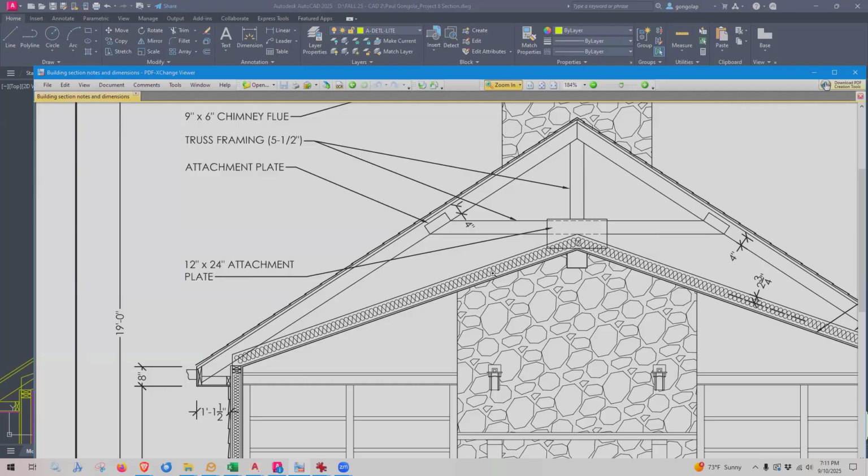You know what? I misspoke. This also is part of the truss too. So all of this framing gets put together in the factory, gets shipped out, and then with a crane they lift it up, and some guys are up on ladders over here. They lower one truss down, they attach it here, and then they put the next one in 16 inches, and then 16 inches further and further until they're all up. And then they'll often have bracing that runs in between them.